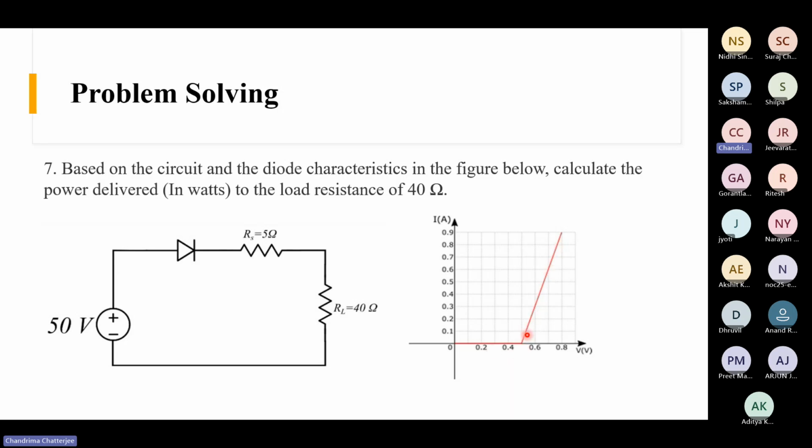This is again a piecewise linear characteristic. So our resistance will be constant because the relationship between current and voltage is linear. But here you see, they have not given the RD straight away. You have to calculate it from this slope, right? They have not, like in the other problem where they gave the RD value as some 0.85 ohm. Here you need to find it by yourself.